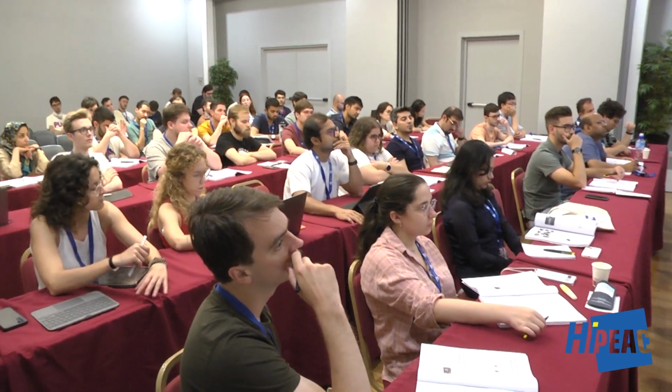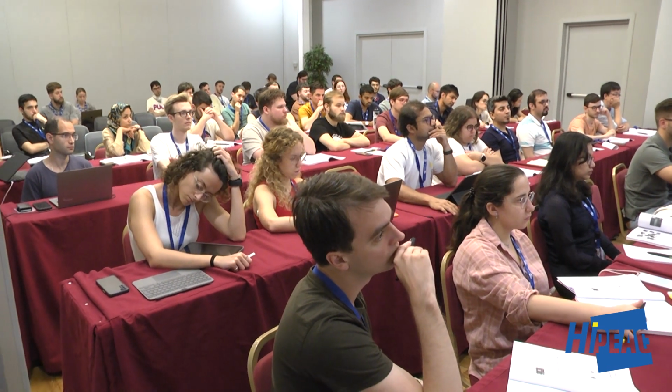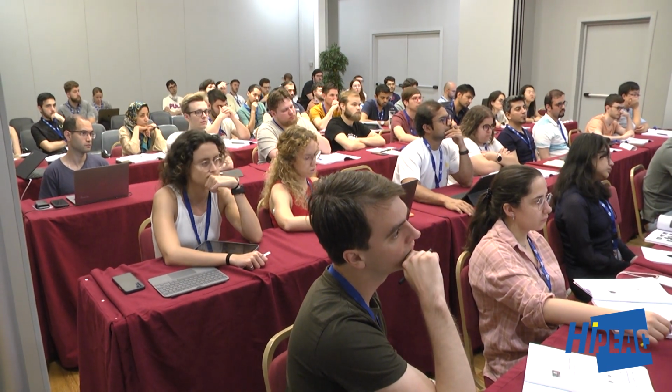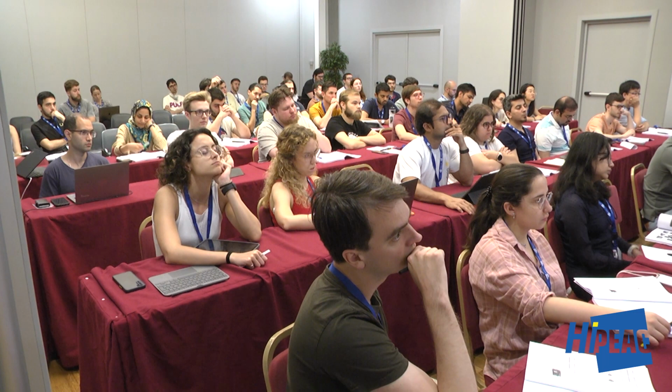Yeah, there's a hand there. Destructive operations. Destructive operations, yes. So data is destroyed when we compute something. So if we still need the input, we need to copy that. Yeah. For that, or we need, well, yeah, very clever insight. But for which one? Would it be for SRAM, DRAMs, bitline, analog? It would be the case for DRAMs. Not for SRAM or memristors. Yeah.